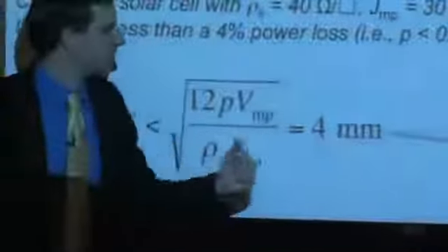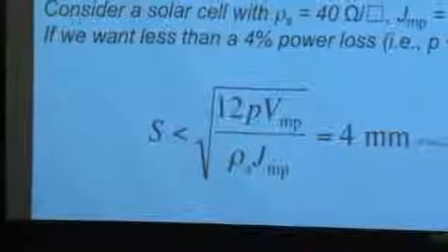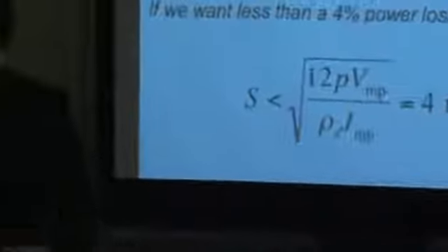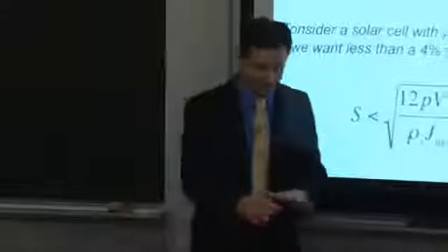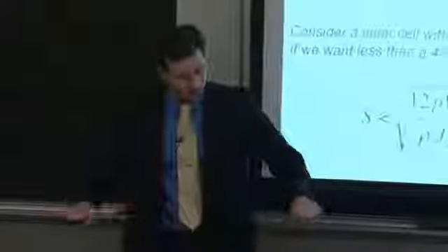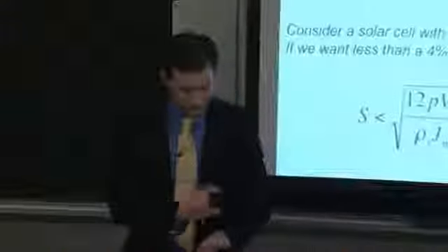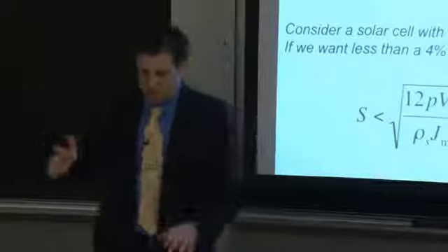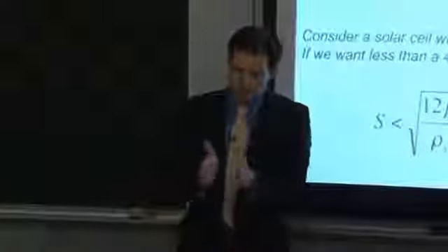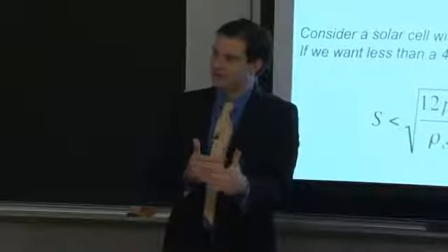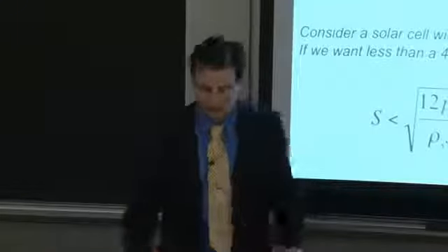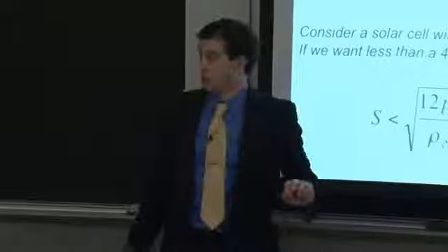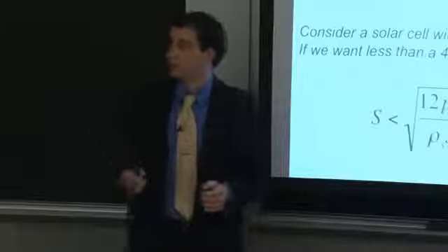So this is interesting. We have now the appropriate spacing between fingers. It's about 4 millimeters, which means if we're going to be making a solar cell device, say a thin film solar cell device, on a sheet of glass with some transparent conducting material, some transparent conducting oxide, now we have our solar cell device and we have the front surface here, and let's say something else on top. We have to limit how wide we make that device. Otherwise, we could be limited by our emitter sheet resistance in, say, the zinc oxide layer of our device.